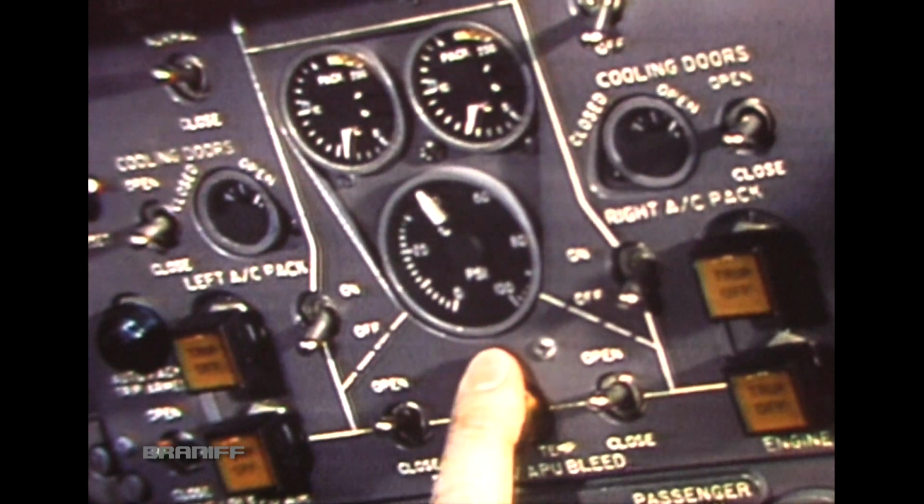Other precautions are also required. Wing surfaces must be clean. All control surfaces, including leading edge devices and slat gaps, must also be clean of ice, snow, or frost. Check hinges, tracks, and actuators for trapped moisture, ice, or snow, and de-ice as necessary.